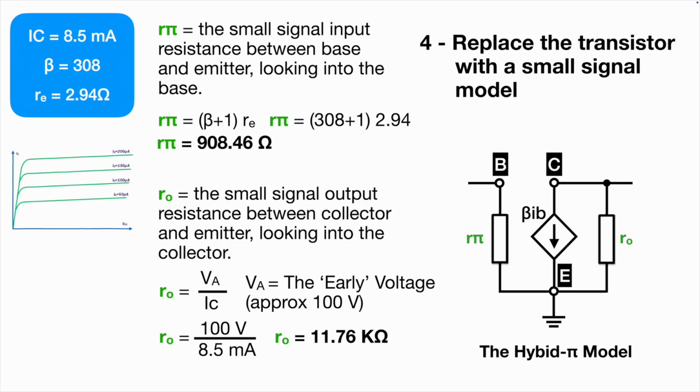And you remember when we talked about the ideal voltage source and how we were able to short circuit that to ground from an AC perspective, because an ideal voltage source, of course, has zero internal impedance. Because if you think about it, even if your desktop power supply had a little bit of internal impedance, whatever you connect to it, you've got a voltage divider effect. So you won't be getting the full amount of voltage because some of it is dropped within the internal resistance of the device, right?